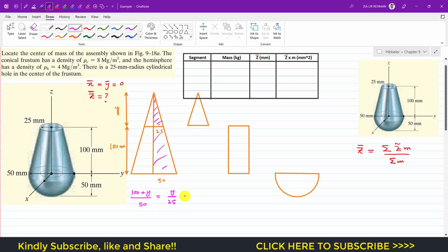If we cross multiply, 100 plus y divided by y will be equal to 50 divided by 25, which is 2. If I multiply y on both sides, we have 100 plus y equals 2y. If we bring this y to the other side, it becomes negative, so 2y minus y is y. From this we can say that y is equal to 100 mm.